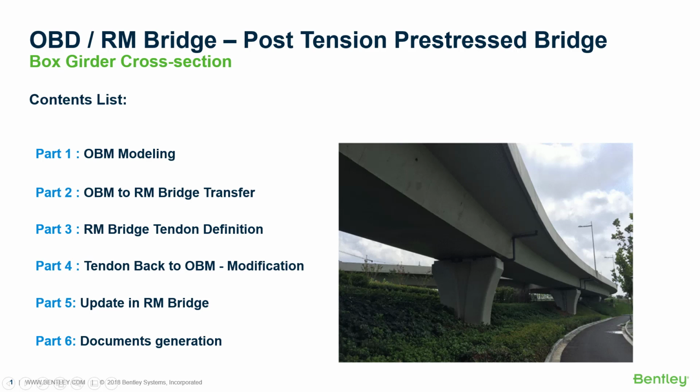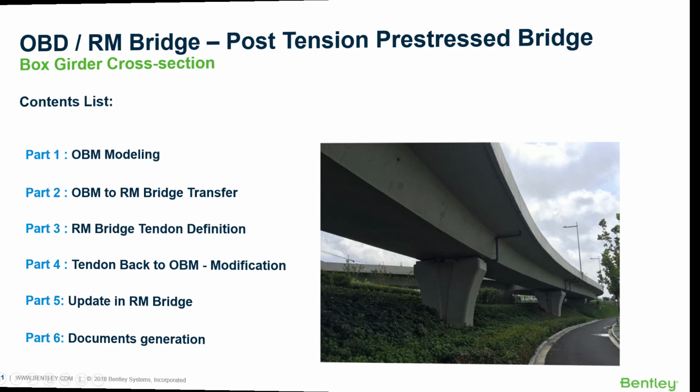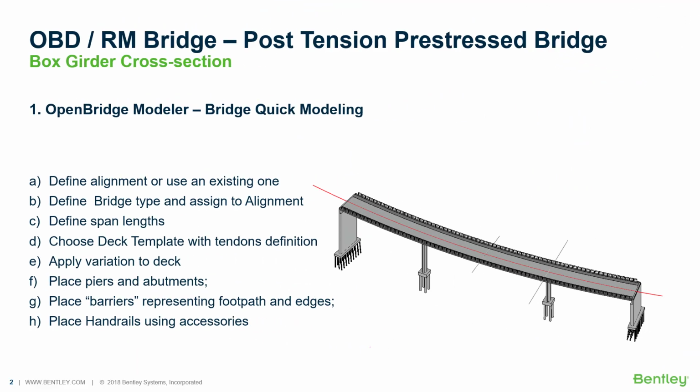We will see in this presentation how to create a post-tension pre-stress bridge. First, by modeling it with OBM, transferring data from OBM to OpenBridge for the analysis, then the tendon definition, what happens in case of modification, and finally drawing generation.